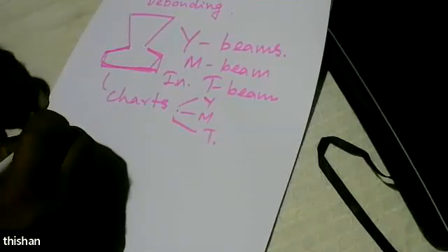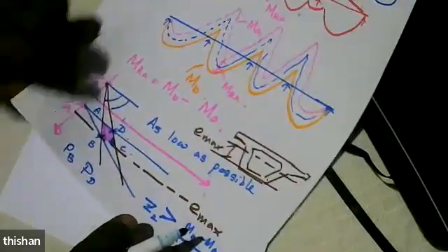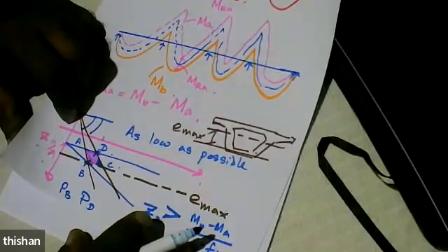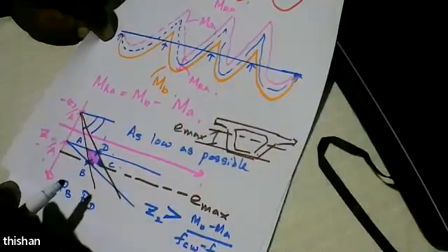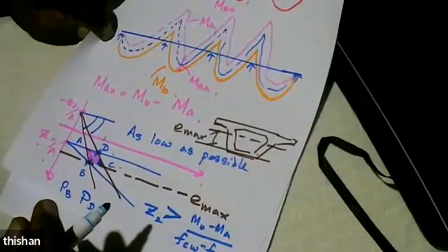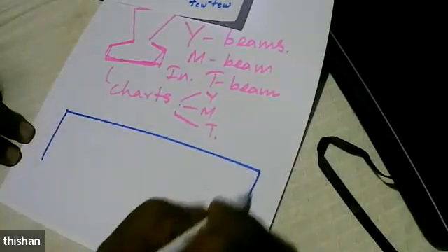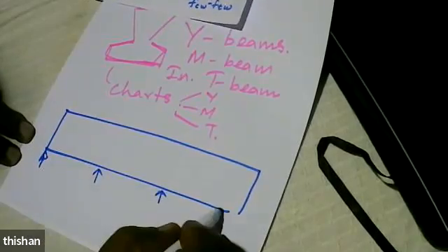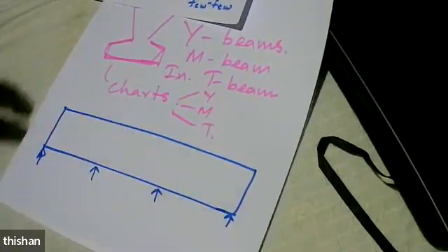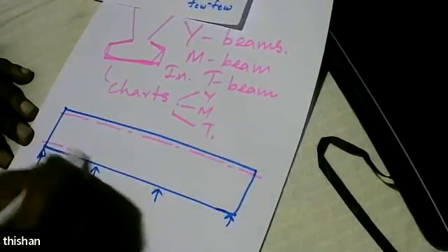So we have a bending moment diagram. If you have the maximum moment and minimum moment, you can draw a bending moment diagram, and then you can select a pre-stress, and if you select a sufficiently large pre-stress, these are your maximum and minimum boundaries. You can't place any tendon beyond that point.